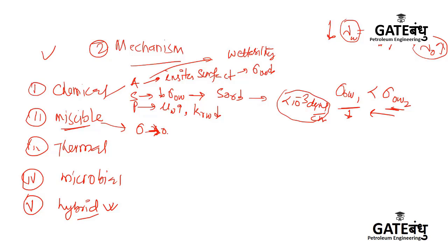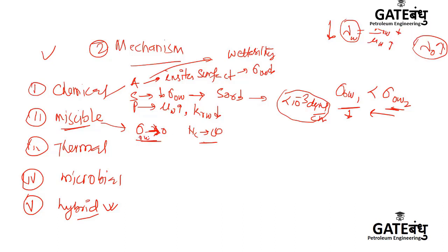And when surface tension is close to zero, the capillary number reaches infinity. And that is the case where, for oil, it is like a highway. They are running on the highway. And that zero surface tension between oil and water is achieved through what is called mass transfer, the basic idea.